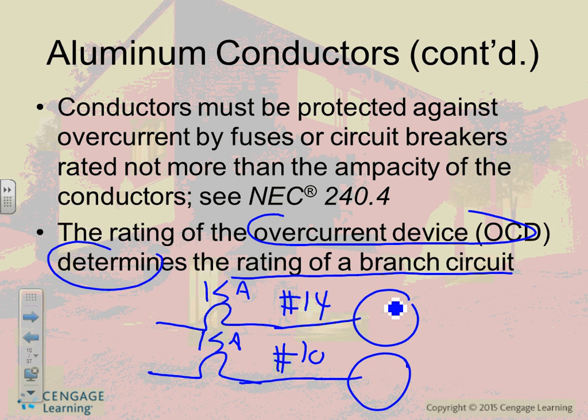15. You don't look at the conductor when they ask what's the rating of this branch circuit. They go by the circuit breaker or the fuse. They don't go by the conductor. Why? Where would you use number 14 indoor? Where would you use 15 amp on number 10? Parking lot. Why would we use a bigger conductor than number 14? Are we nuts? Have we lost it? No, voltage drop. They use it all the time.